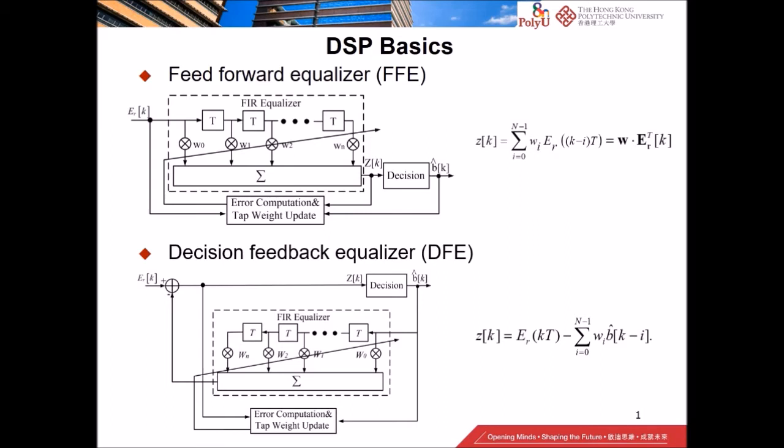In our case for fiber optics, since one of the major transmission impairments is chromatic dispersion, it induces intersymbol interference that contains both interference on future symbols and past symbols. Therefore, the best choice of equalization is always a combination of the feed-forward and feedback structures. In addition, one can use concepts such as Tomlinson-Harashima precoding, the transmitter side DFE. It can be used in our scenario, and it does not suffer from error propagation.